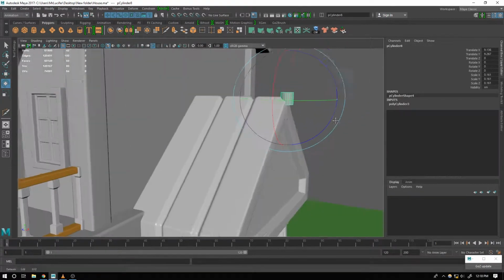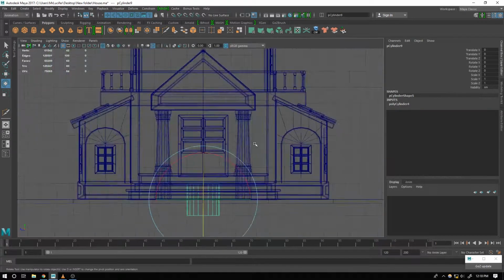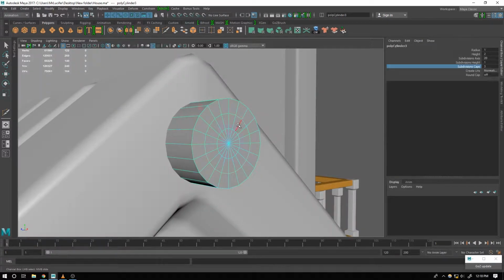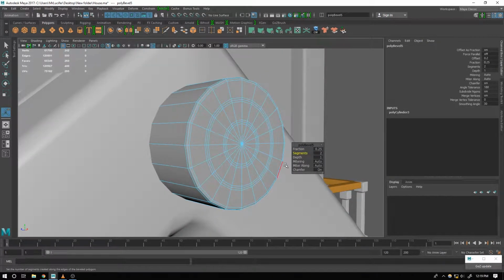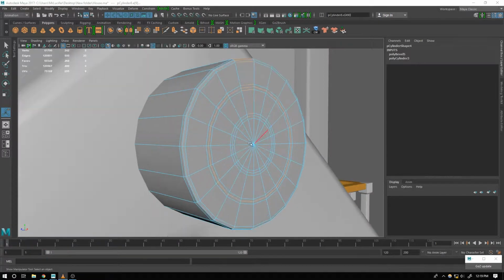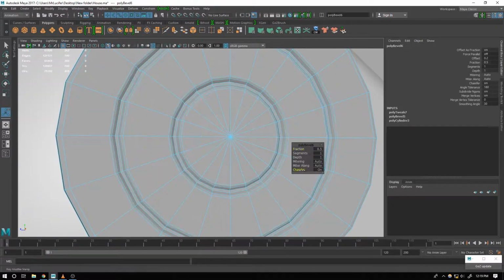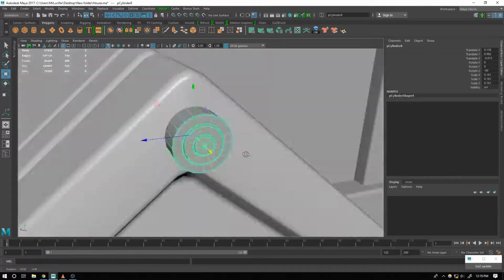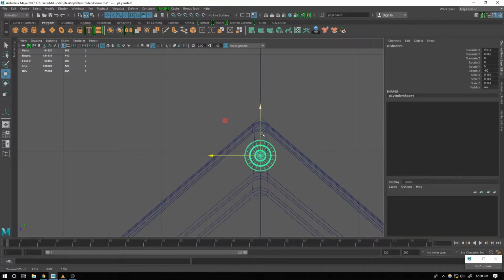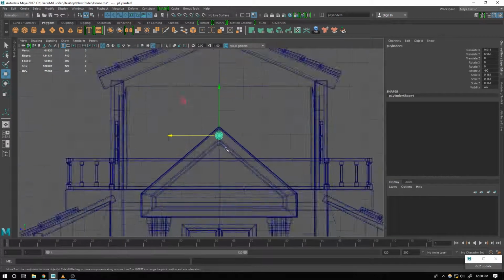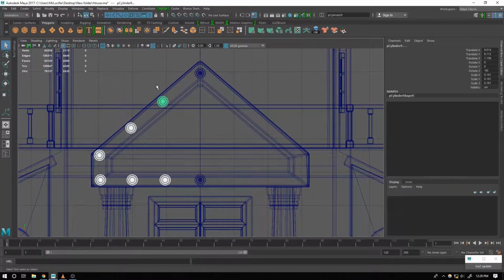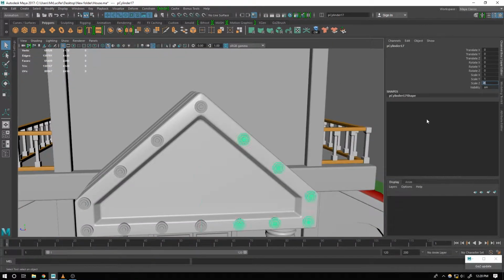Now the design decoration part, I add a cylinder on that ring. So now I am aligning it with the surface of the top triangle design, and now I just bevel those edges and push backwards, and I'm trying to give a kind of little breakage, so that when the shadow casts from there, it will give some shadow. That's why I'm making that middle circle forward.